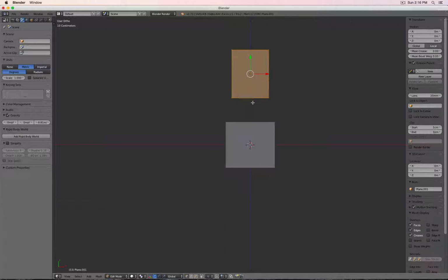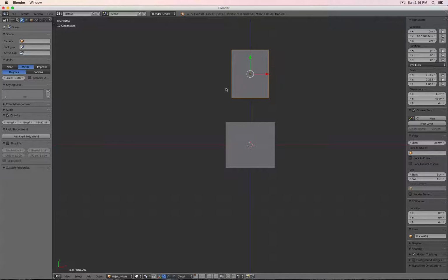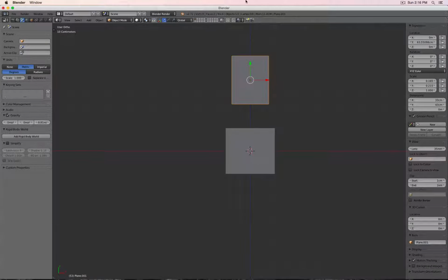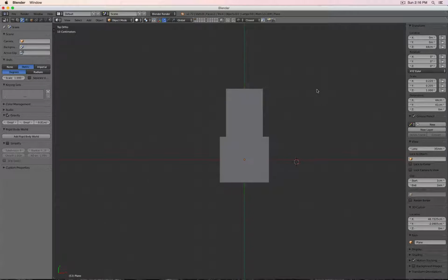Okay, now I would like to change the layout or the positioning of those two shells, and I switch to edge snapping, move this one down, hold Control and snap it to this part, and then I can move everything 44 centimeters off the ground, so it has the right height. Okay, perfect. So why did I do this?